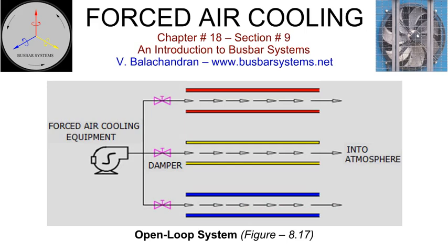The inlet to the isolated phase bus is normally indoors near the generator. The air travels through the annular space between the conductor and enclosure of the bus. It is discharged to the atmosphere at the far end of the isolated phase bus, near the generator transformer. The airflow rate can be controlled at the inlet of each phase to ensure a uniform temperature at the outlet of each phase. The temperature of the conductor and enclosure will be higher near the outlet.